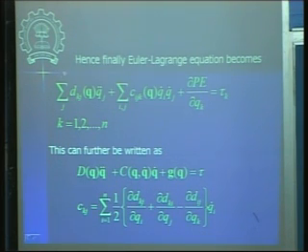So you get here the contribution in terms of acceleration terms. These acceleration terms, you can see, are basically because of the parts in the kinetic energy expression. Okay, dij were the parts in the kinetic energy expression. So these are the elements of the kinetic energy matrix D. Okay, you remember how we expressed our kinetic energy? It was basically half q dot transpose D times q dot. Okay, and then this D matrix has these dij terms which are appearing in the acceleration terms to multiply the acceleration of the generalized coordinates.